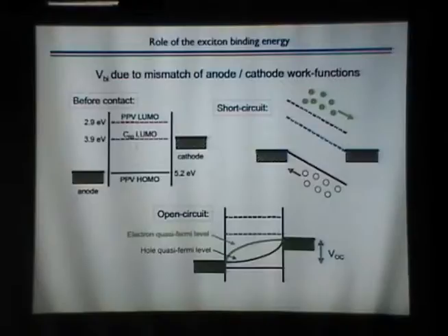And the only way then to meet the requirement of them lining up is for there to be a tilt in the bands. And so in this axis is energy, this is distance, this is energy, this is distance. So now you've got a changing energy with distance. You have a dE/dx. And from second semester physics, you know that's an electric field, right? So now I've drawn a constant electric field in that device.